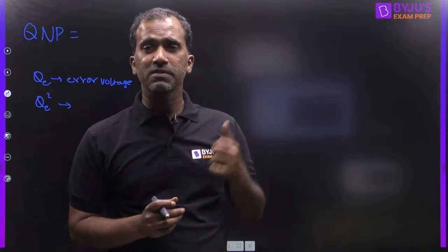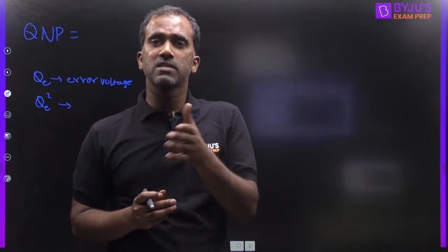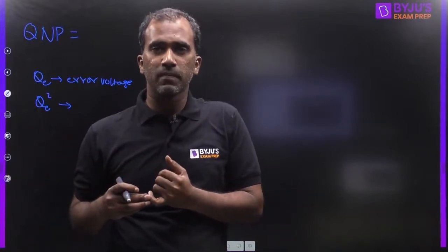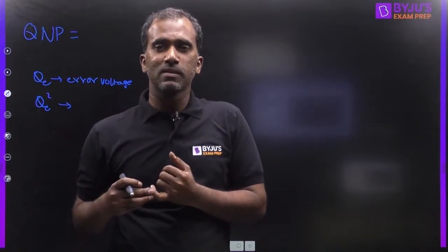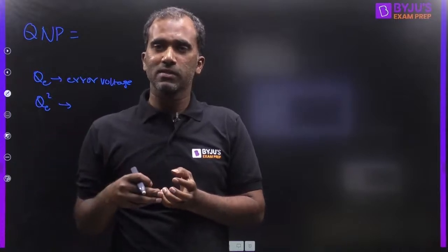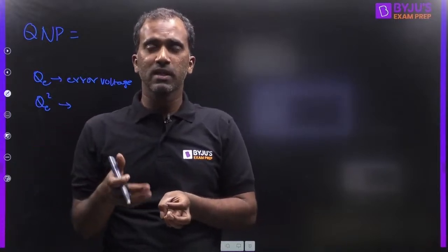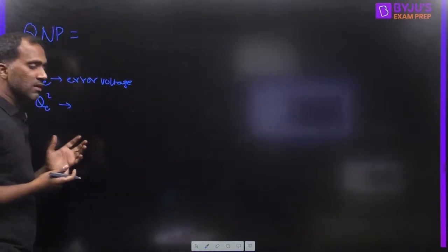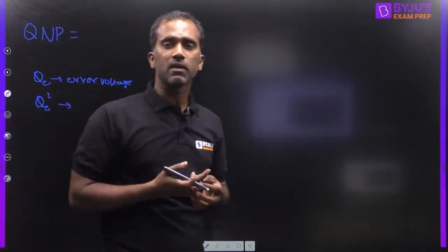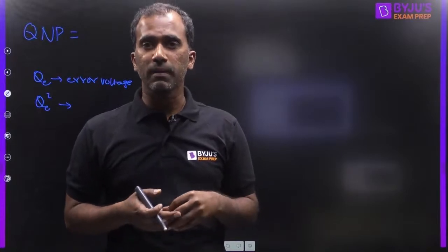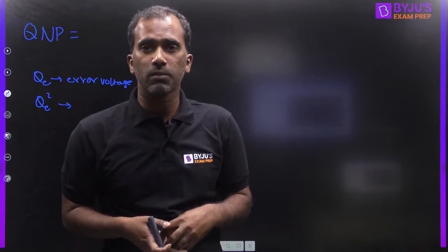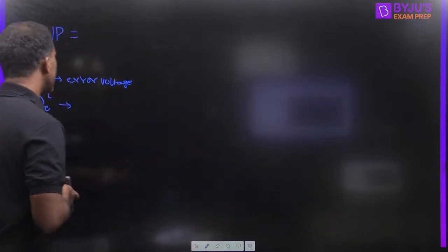And in the previous slide also we have seen quantization error, we have written it as x minus delta by 2, x minus 3 delta by 2. In different regions we have written differently. Since quantization error is dependent on x, if x is random, quantization error also is random. For a random signal or a random variable, how do you find the power? You have to find the mean square value. For a random signal, how do you find the mean square value?